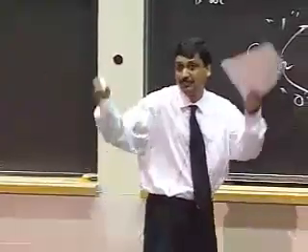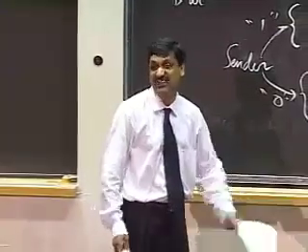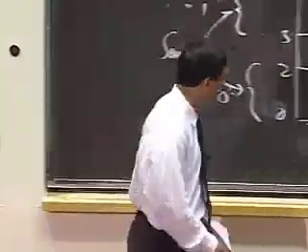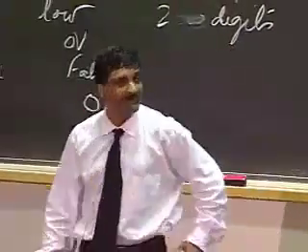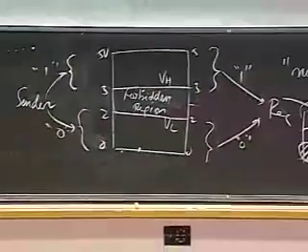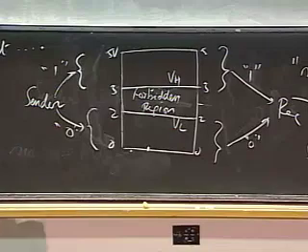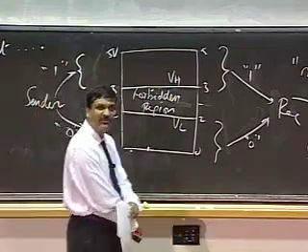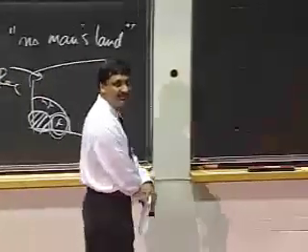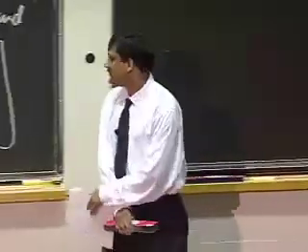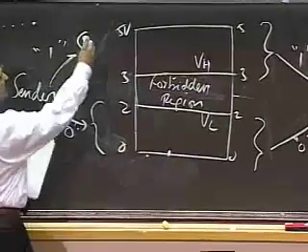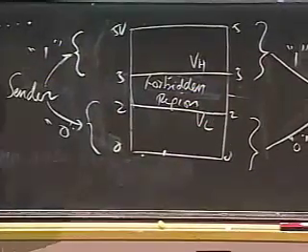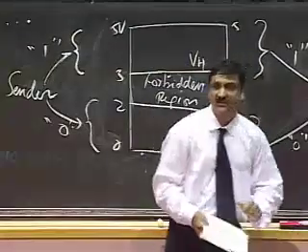So you, as a receiver designer, can do whatever you want when you see a 2.5. You can say, I'll just put out a 1 if I see a 2.5 or 2.6. I'll just do something. No one cares. So this is pretty good. We still have a problem, though. Do people see the problem here? This still doesn't quite work. If Intel did this, instead of your laptops failing and blue screening every hour, they'd be doing it every millisecond. So the problem is, with this discipline, I've allowed the sender to send any value between 3 and 5 as a 1, and any value between 3 and 5 at the receiver is treated as a 1.